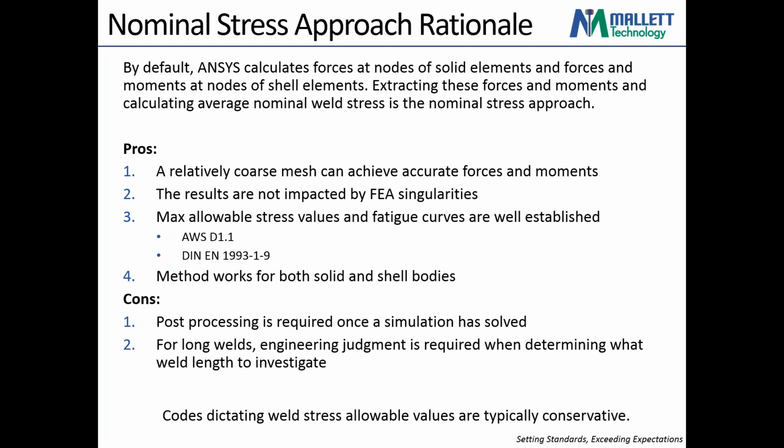So the cons. Some post-processing is required once the simulation is solved. If we solve our simulation, then we have to go in, extract those forces, calculate the weld stress, compare that to allowables, and then justify whether or not it's acceptable.